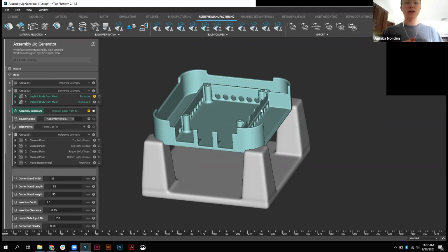done on this part. So for a little more context, if we're working with electronics, we're working with maybe small, very sensitive parts that can be triggered even by the static on your clothing. For those who are familiar with this world, you have to wear proper equipment and make sure you're in that proper environment to work on these parts.